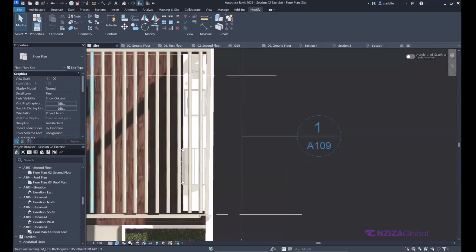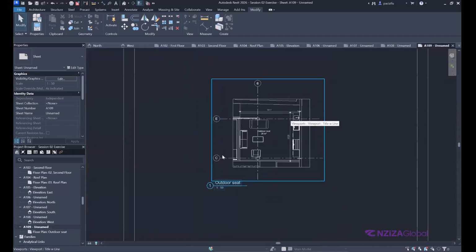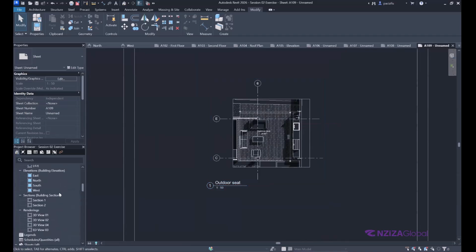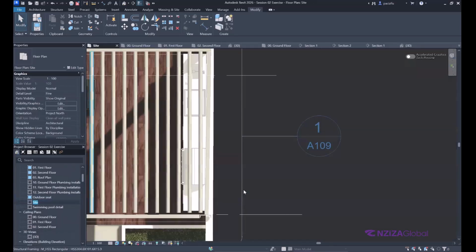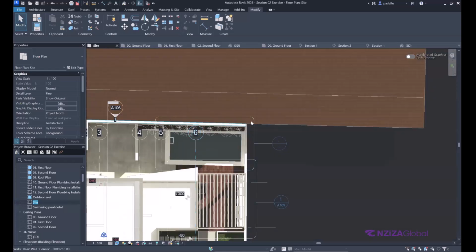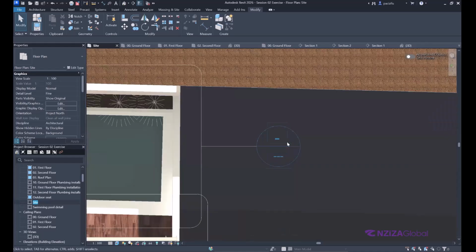So when you go for the page A109, you open it, you will see the 1, then you have details there. Means even this one, if we take this and press it on a paper, now it will get those information of where it is located on a sheet and the numbering of the detail.